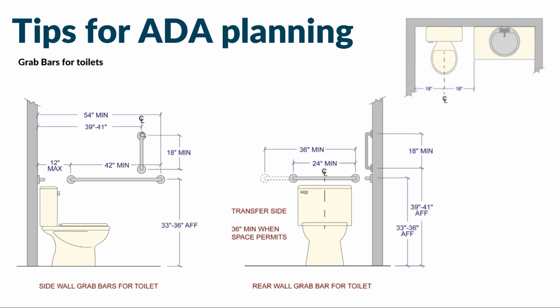Then we'll also have a vertical grab bar that's a minimum of 18 inches, and then from the center, again, 39 to 41 inches out from the wall.